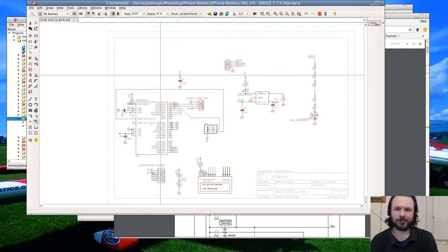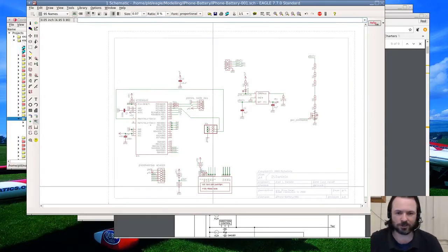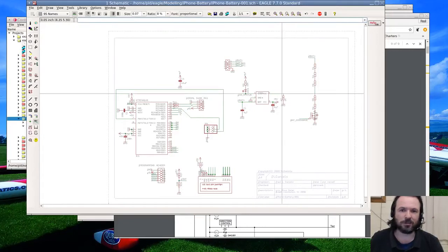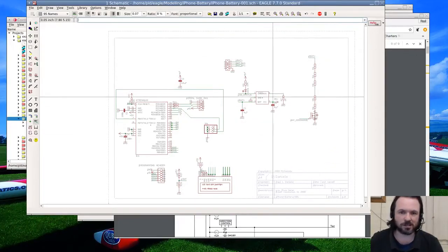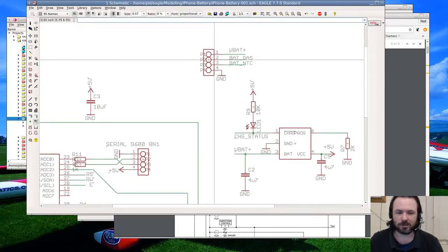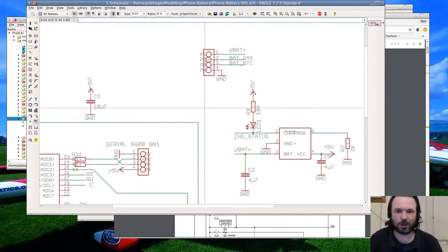Alright, well, realistically, by the looks of it, we've got the fundamentals down. We can flash it, we've got our LED display, we've got our discharger, which is delightfully simple compared to, that's what we need a voltage sense. So, let me think. Now I'm going to be running this AVR at 5 volts, so I can actually just go straight into the ADC with VBAT+.